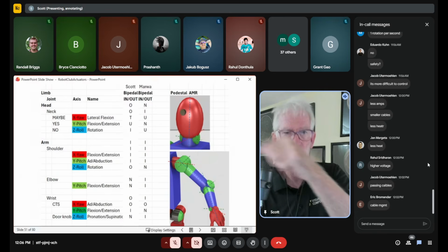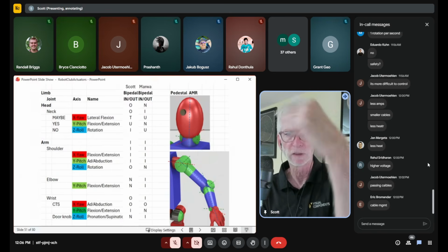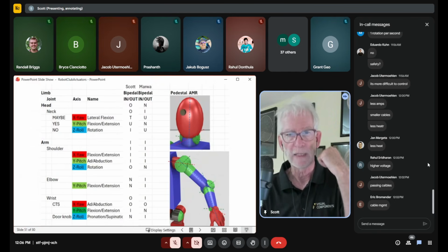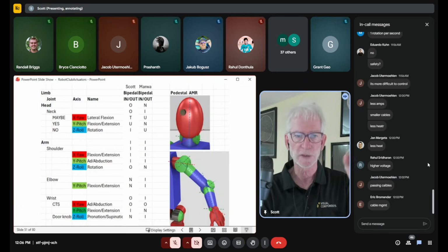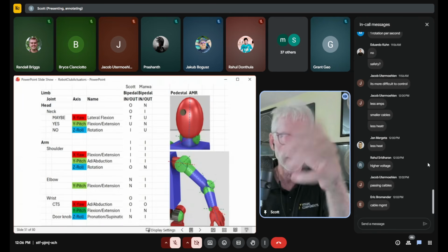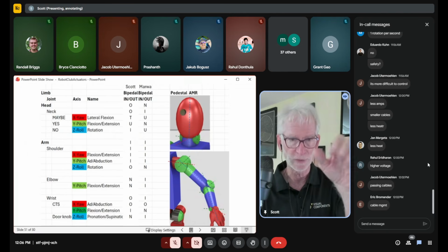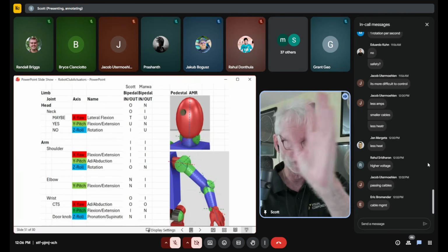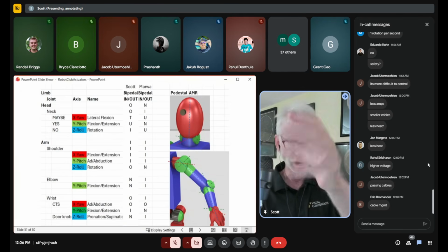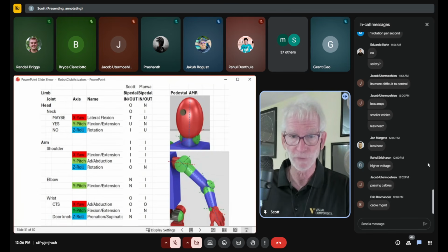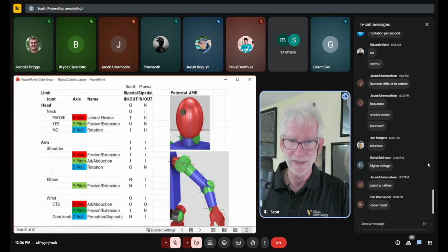The whole purpose of the elbow is to change the distance, the length from your shoulder out to where you need to be. So if you think of this as a spherical coordinate system, it's your radius, gets you out to where you want to be. And then out on your wrist is the stuff that gives you the orientation that your hand needs to be in. And you have to decide how important some of those orientations are to your hand for doing certain manipulations. And you'll see most arms have 7 degrees of freedom, which means there's a redundancy in there.